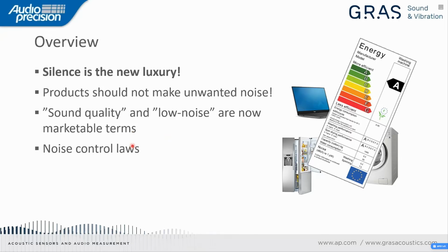But now it's also time to talk about noise control laws, noise control regulations. And I can say they are particularly important, at least in Europe where I live. For example, consumer electronics devices such as computers have to go through noise measurement tests for certification. An example of this is the new machinery directive 2006/42/EC from the European Union. This directive has a section about noise control saying that the noise of the device should be assessed in a way that is comparable with devices of the same category.